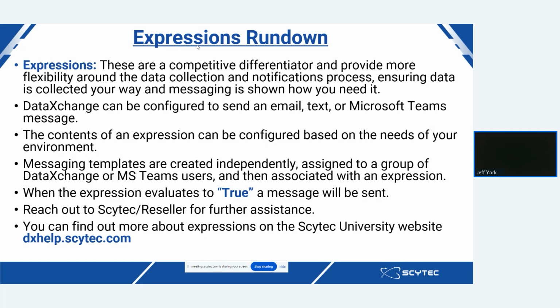As I mentioned earlier, data exchange can be configured to send an email, text, or Microsoft Teams notification messages based off of these expressions. The contents of expressions can be configured based on the needs of your environment. Messaging templates are created independently, assigned to a group of data exchange or Microsoft Teams users, and then associated with a configured expression. So when your expression evaluates to true, a message will be sent.